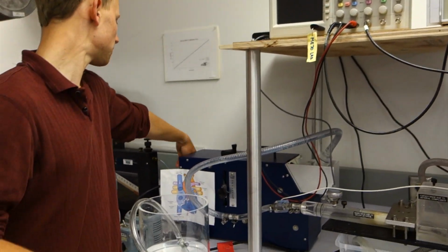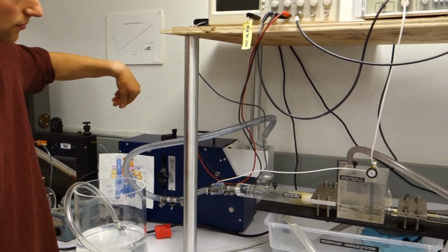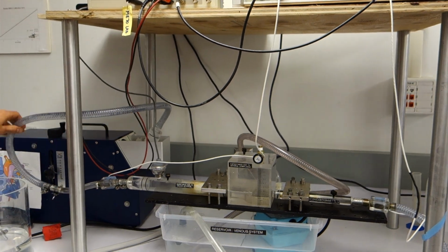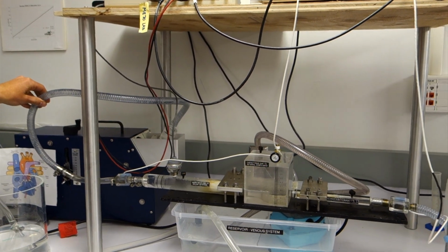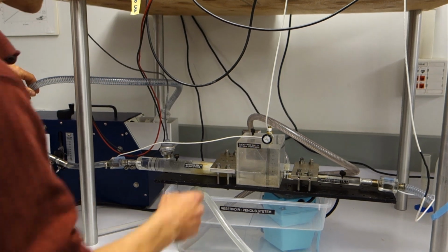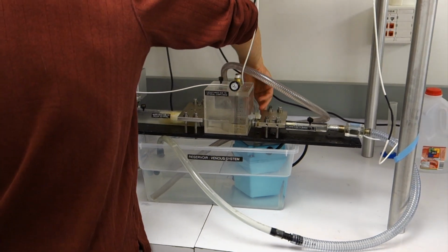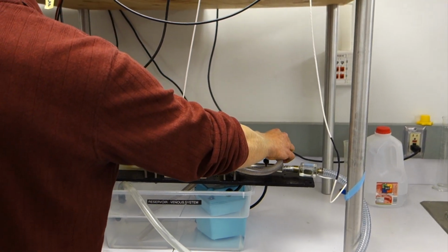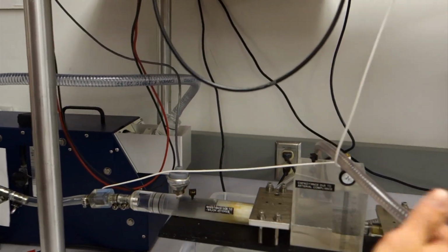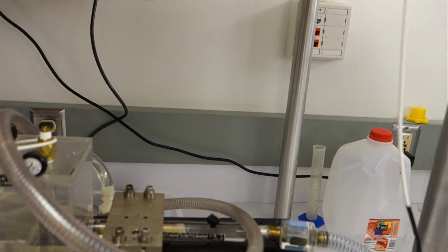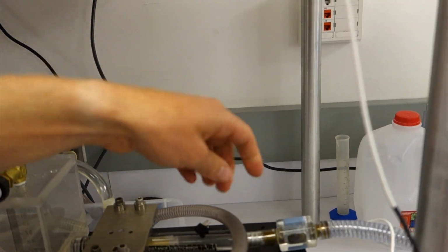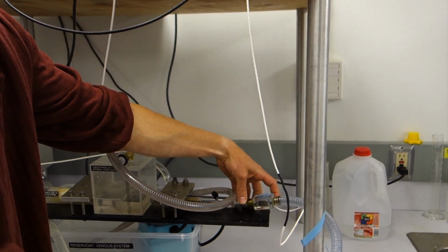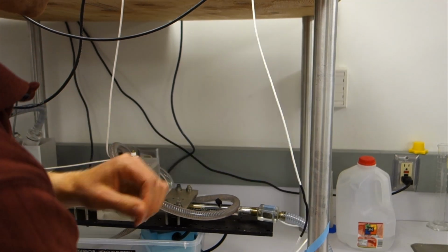Let's turn it on and sort of see what happens here. There's some water, or some air introduced in the system. We'll let it even out and get rid of all this air. Sometimes it requires some TLC to do that. Getting there. If you look closely, you can see bubbles that sort of move and then stop and then move and then stop. There's some air in our flow sensor. Now whenever there's air in the flow sensor, we're not going to get a good reading for the flow rate, so we got to make sure it's just smooth, as laminar as can be.